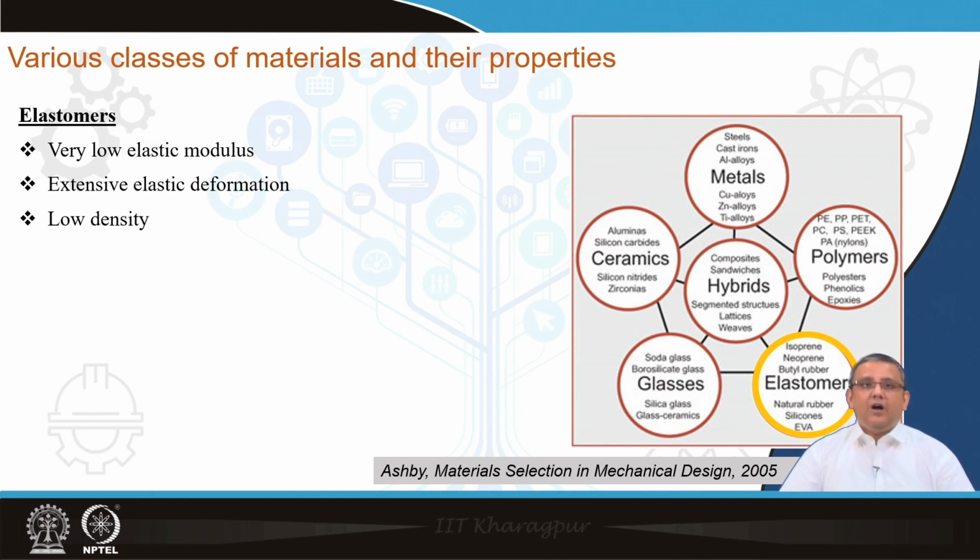Elastomers are another very important class of materials in our day to day life, like the rubbers that we use. Elastomers are basically a kind of polymers where the individual polymer chains are cross linked with some kind of weak bond, and when an elastomer is loaded in tension, these cross link regions provide some resistance to displacement of the chains, and that provides elastomers with good elastic properties.